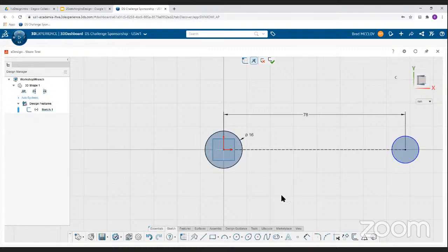So another thing we had on our first wrench, we had a handle. So I'm going to click the line again. You can see there's 2 points on here. And we can automatically start to build in relationships or constraints. So see how there's a circle on here? Basically, if I start the line and something's highlighted blue, it's going to do a constraint. We're going to constrain it to that line. It'll be coincident with that line. So the start of that line will be coincident.